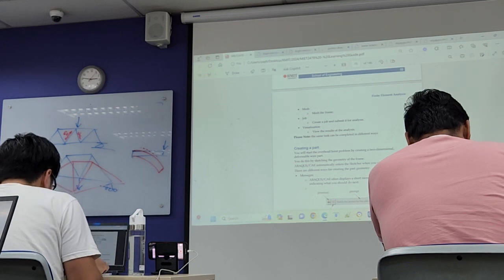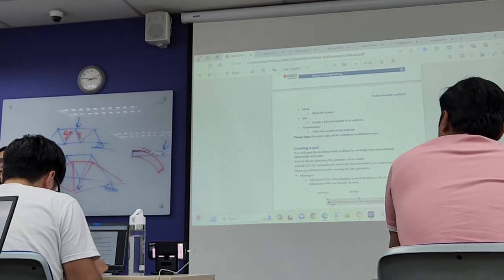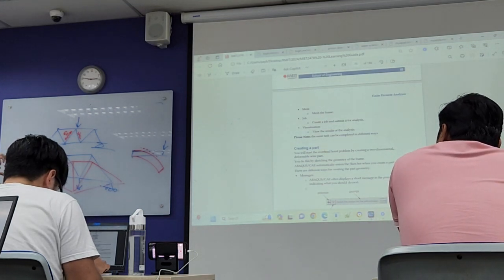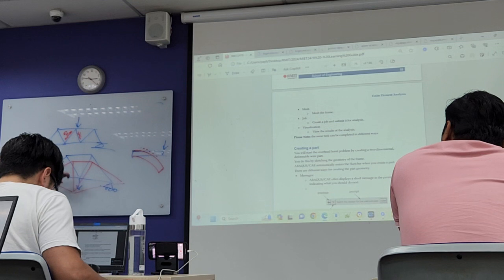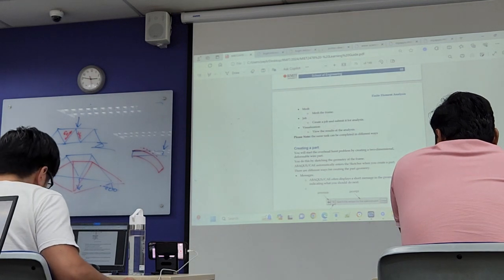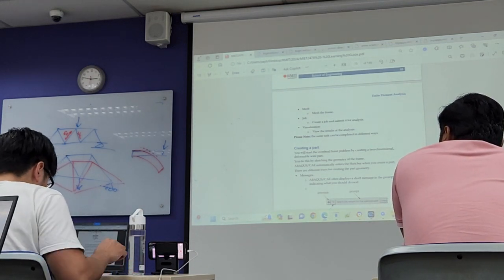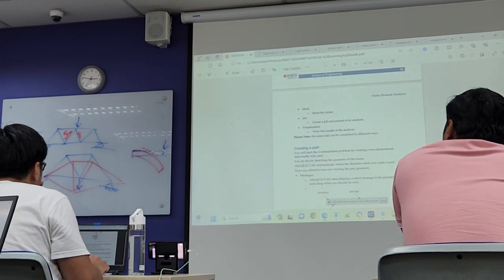And the reason is because most of the time, in the truss structure, the connection is actually a pin hinge. It's a pin hinge, whereby you allow it to rotate at the hinge. That's why you don't carry forward any moment. Okay? If you want to understand, you must let me know. Because I did just some background, then I will go into the actual part of this.